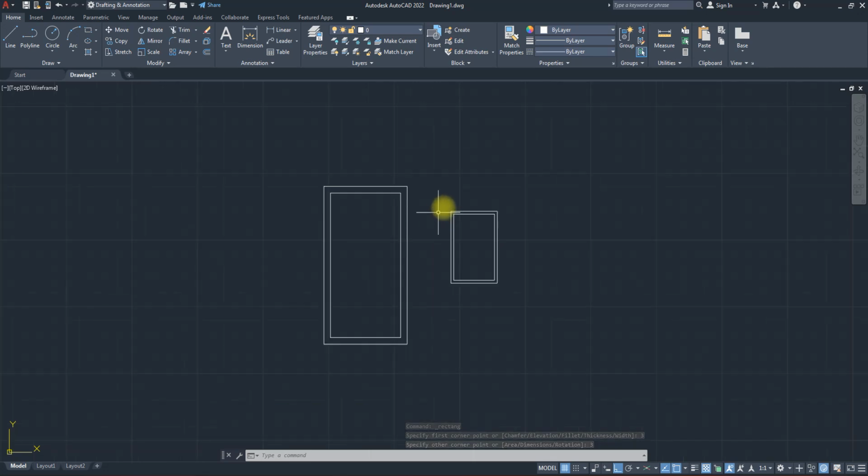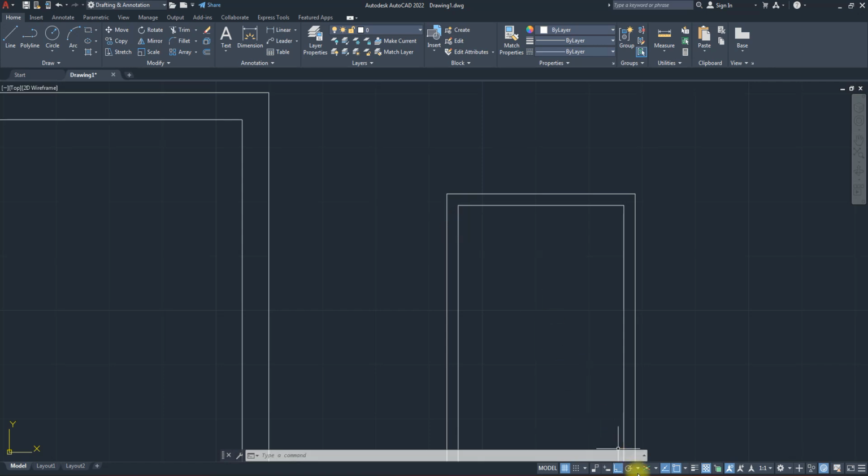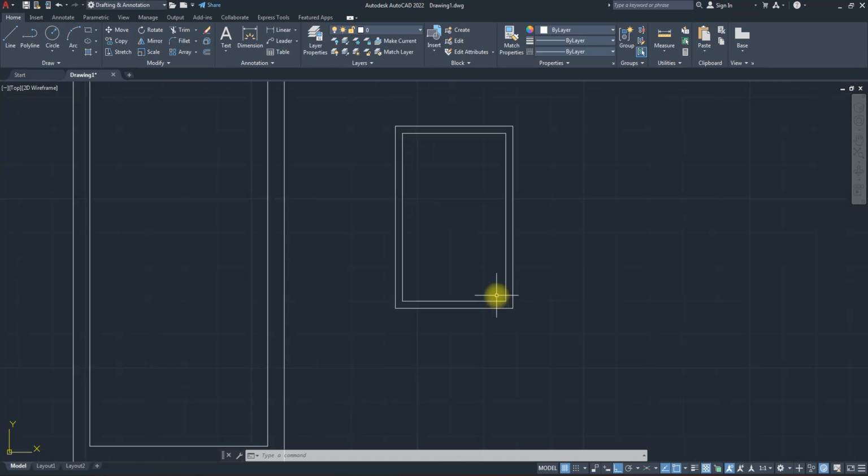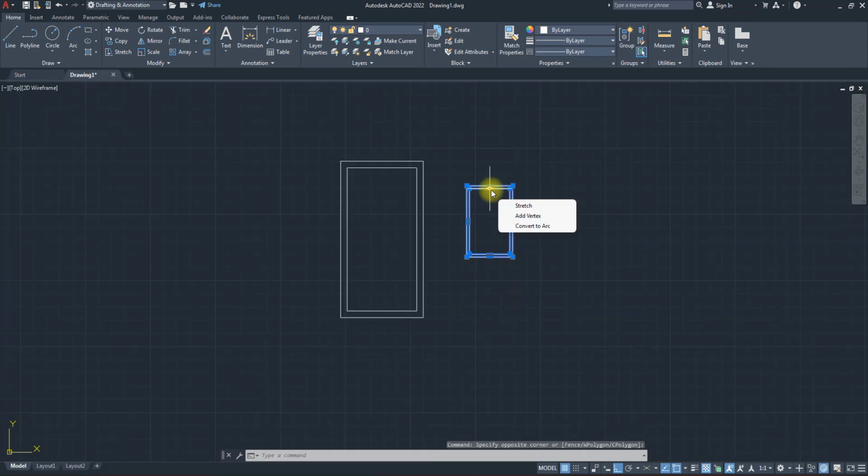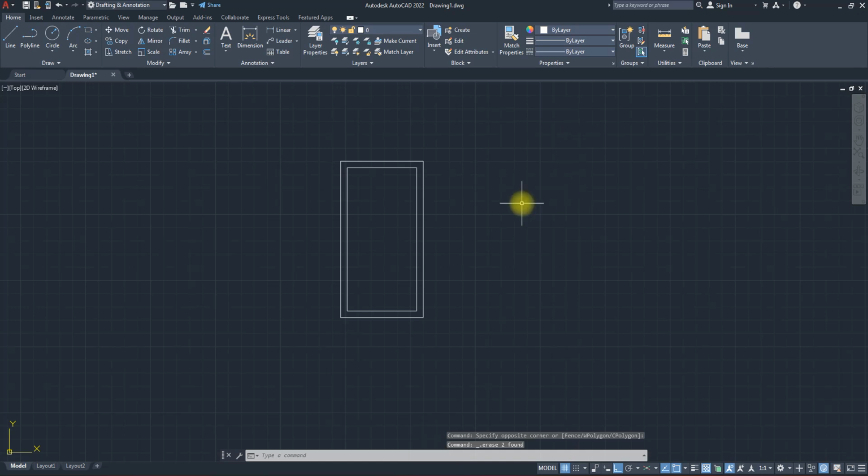Do you understand? Mind you, I did two things. I turned on this 45 degrees. Then I moved in at a particular distance from this corner, and whatever distance I use for this corner is the same distance I'm going to use for this corner, to be sure that everything is the same. But all these things are still long. You can actually create those two lines at a go. You don't have to be creating one by one, and for us to do that, we're going to use a tool we call multi-line.